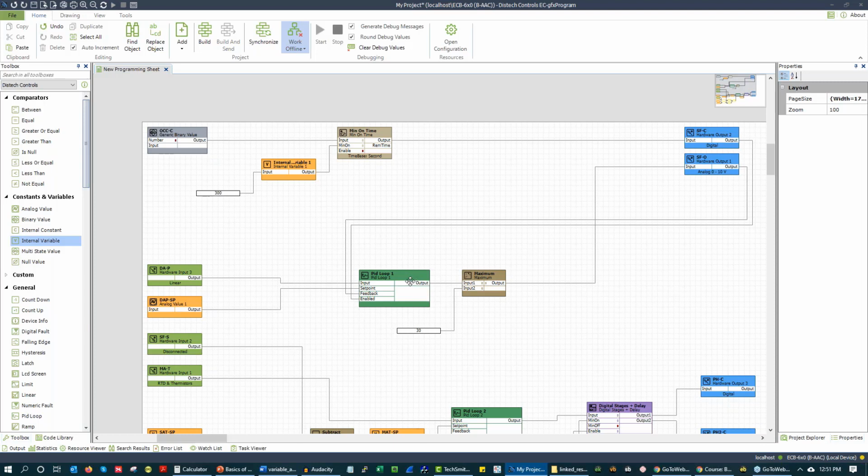Problem is, you show up on a job site, you're like, what are you doing? You don't override that. And you release it, and then the loop's all going erratic, and it looks like you're having an earthquake if you look at the trend log. The way to avoid that is to take the feedback of the output, feed it into the PID loop, and the PID loop will know that the output is overridden, and it'll say, hey, this is overridden. I'm not going to keep winding up. I'm going to understand that someone has done something they should not have done. So that's why.